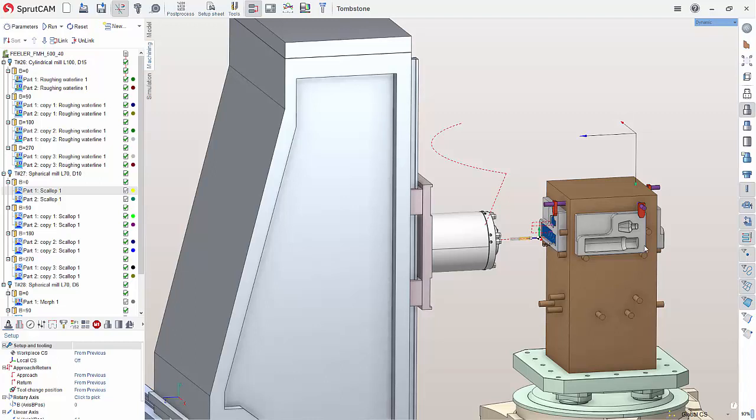Okay, so there were changes made up front with the structure section of this. Essentially, the way I personally look at it is that if you are machining one side and one side only on a part, that's your project, you're just machining one side of a part, feel free to get in there. When you go to structure, you can simply just choose part, bring your part in, add a vise, set your work offset on it, and then carry on.